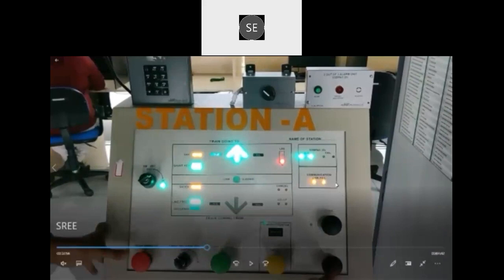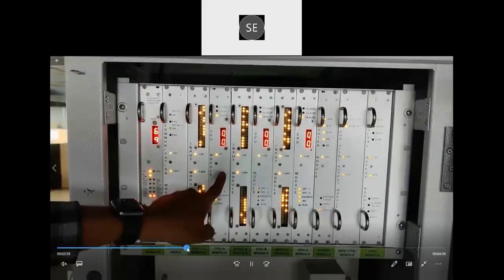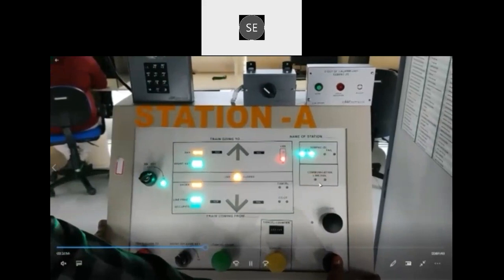This communication link fail indicates the interblock communication with the other end block instrument. If it is blinking, it means communication is okay with the other end block instrument. If it is glowing steady, it means there is a communication fail with the other end block instrument. It has to blink like this, so it means the communication is okay.